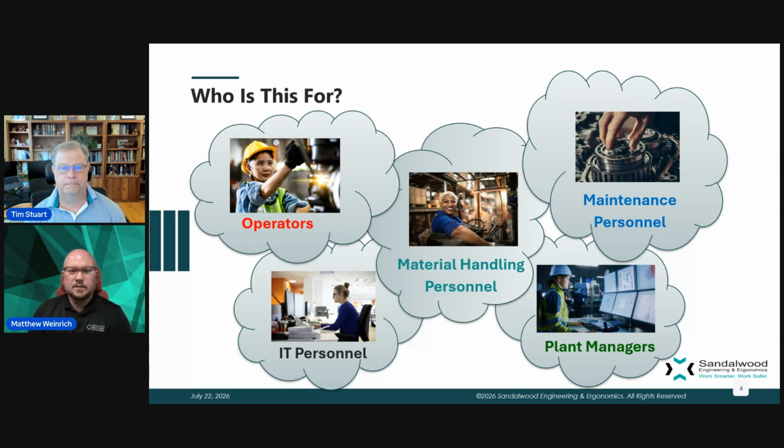Maintenance personnel can see when machine issues are impacting the flow of the line, and if there are particular stations that need priority, if you have multiple machines down at the same time. So this is some of that overlap with some of the other plant floor systems. You might be able to see those machine states in another location, but seeing where all of those are located relative to the flow of parts can tell you, wait, there's a bunch of parts waiting for this one station. We need to really prioritize this one to keep the line flowing, whereas another station might be a little bit less time sensitive to get serviced.